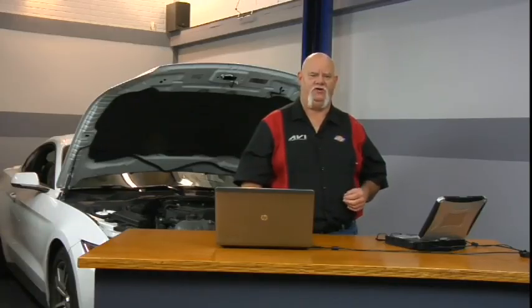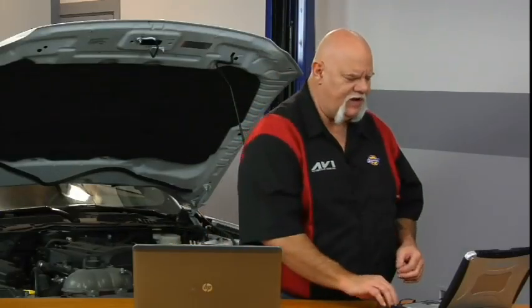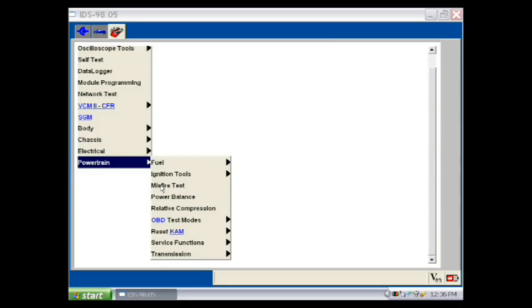So we believe the customer. There are misfires occurring, and through some research, it seems to be a common problem with the EcoBoost engines, cold engine misfire, typically after they've had about 20,000 miles on them. Even though we don't have any diagnostic trouble codes and our fuel trims look okay, I want to cover some system tests that are available to us in the IDS. Make sure we cover all of our bases. The first test I'm going to go to is a misfire test on the IDS.